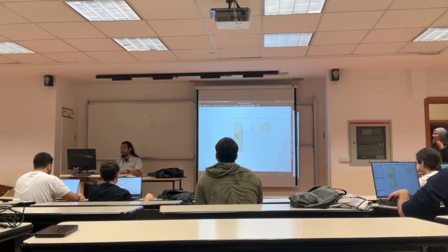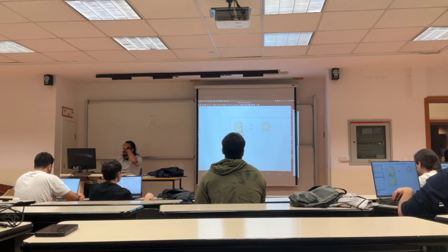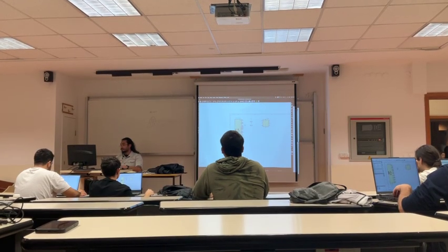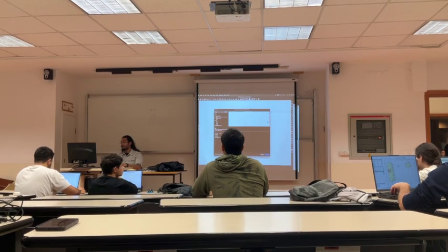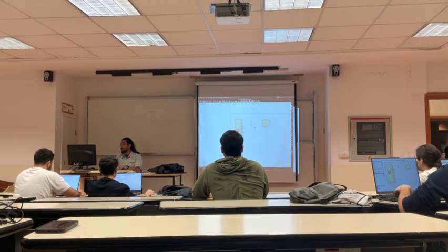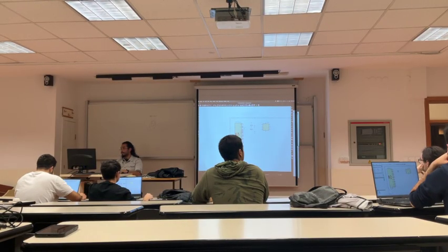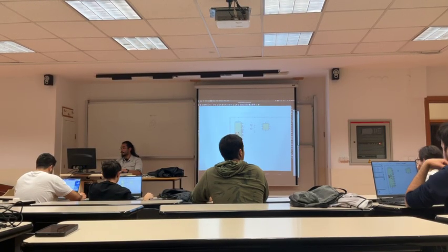As you can see, D-2, there is two of them. CC1, CC2, there is two of them. So we are going to connect things twice. I come here, I press on P again. I come to ground. Bam, I put it here. I put it here as well. And then I connect these two, just like that.